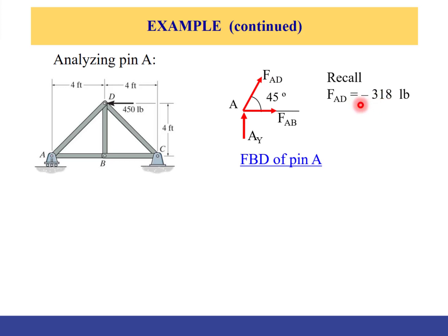You don't have to make any changes to the direction. Just keep the same assumption but substitute the exact value you got. This way you are consistent. It's so easy to make mistakes here. As I mentioned, if you assume it to be in tension, let it be in tension, right? Don't flip the direction on that. But when you substitute, use the value with its sign.